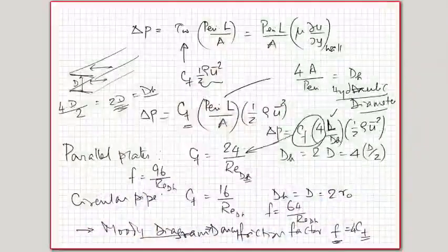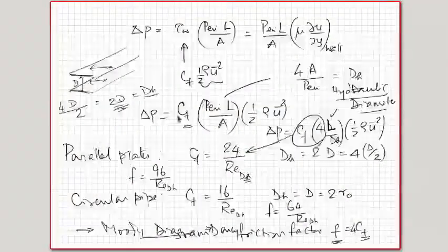We all understand that when there is heat transfer, the temperature profile cannot become constant, because the temperatures undergo a change because of heat transfer. So it's not correct to say, unlike in the case of velocity profile, that in the fully developed region the temperature profile becomes invariant with x. It is not correct. But then something becomes invariant. What is it? That is something that we will see today. So let's go to the whiteboard and start understanding what becomes constant with full development.